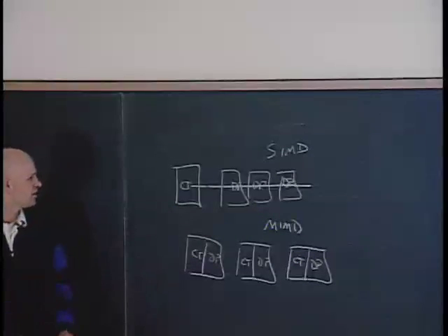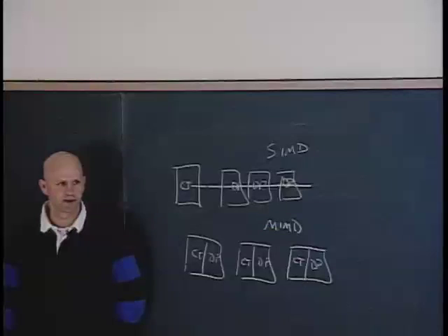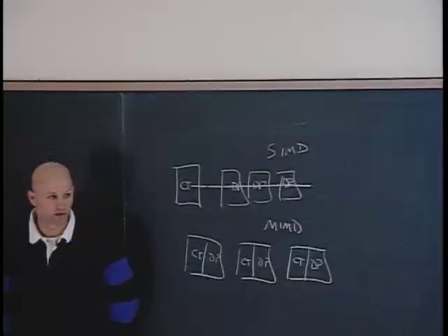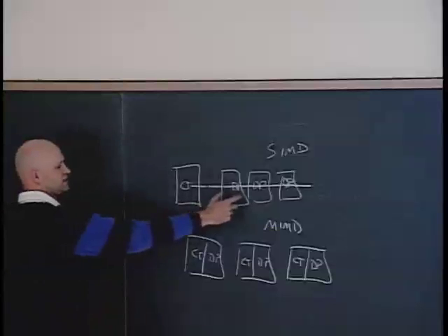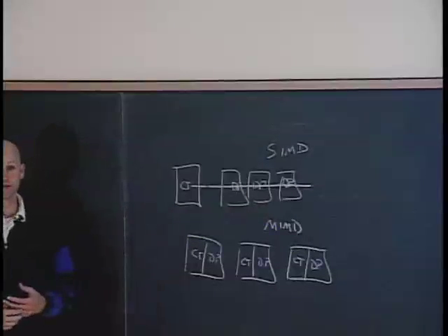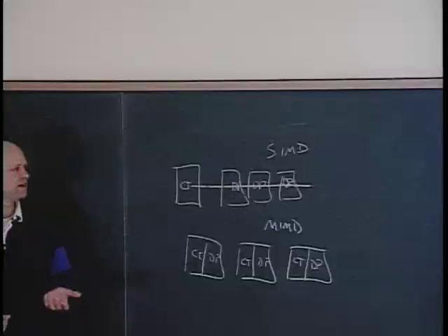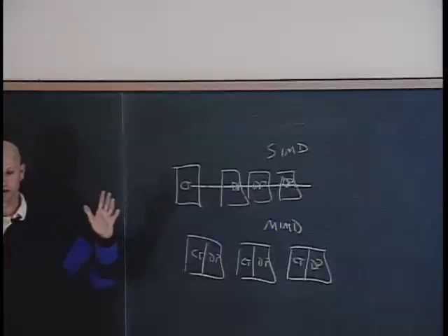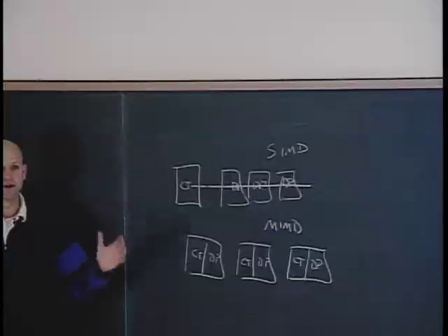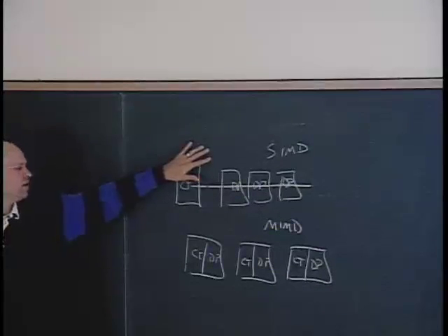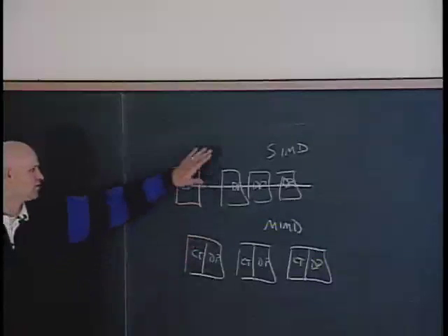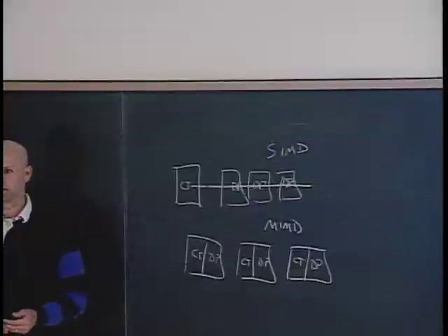Just as an example, I did my graduate work building a processor called Imagine. It was a stream processor for doing multimedia kind of stuff, and it had a lot in common with what graphics processors look like today. In Imagine, the size of the data path was roughly the same size as the controller. Imagine was a SIMD machine with 8 arithmetic clusters, so a cluster was the same size as a controller. We could either have 8 clusters and run in SIMD style, or 4 clusters and run in MIMD style. That's roughly the trade-off. So moving from one to the other costs you half your peak performance.